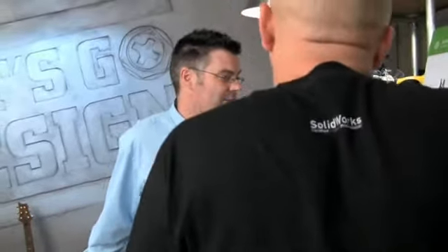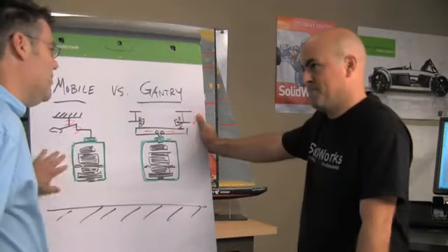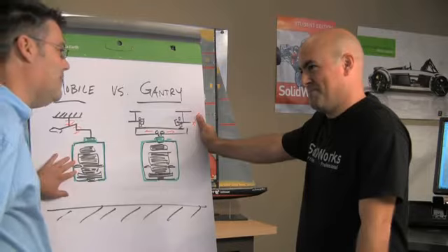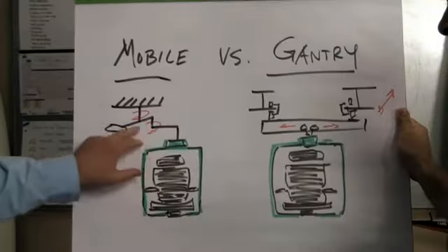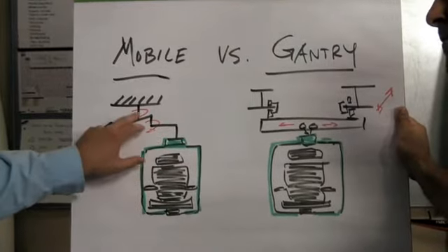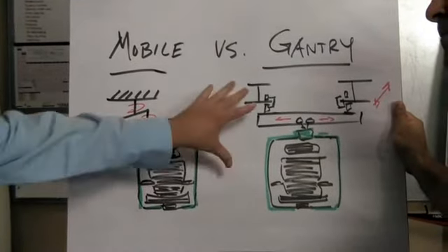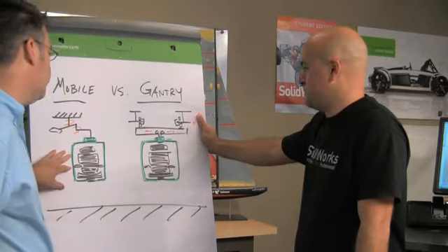Okay, so my first thought is it's a really cool design to start floating around my office, and I'd quite happily have one. Engineering-wise, my thoughts with this mobile are that you've got maybe some long arms here. You're going to have a lot of load going through all these joints. There's a danger of lock-up. As you go to the extremes, it might not reach the way you want it to reach.